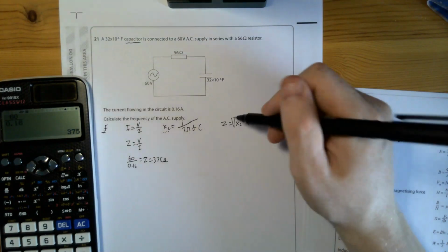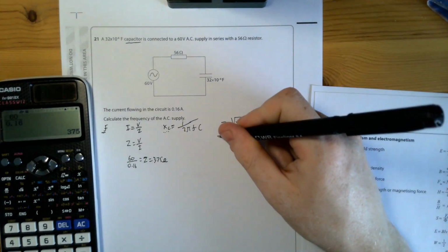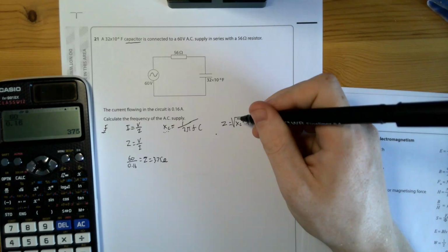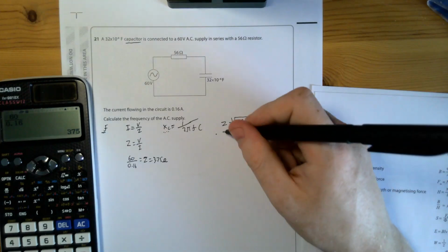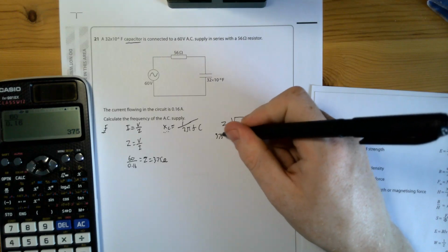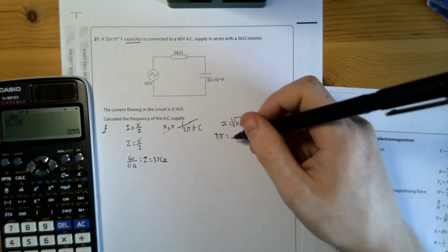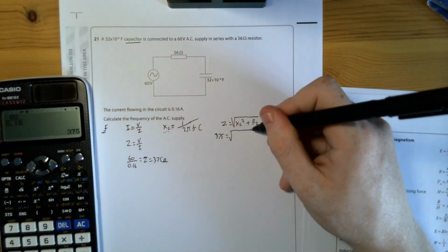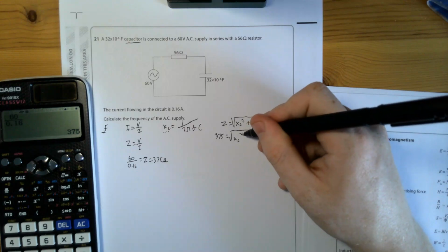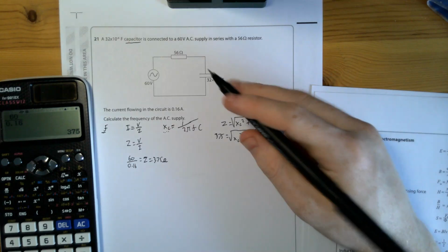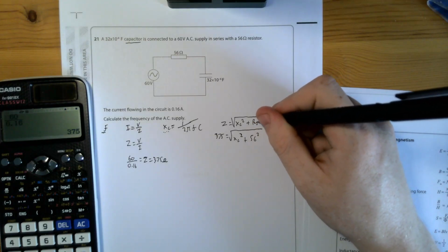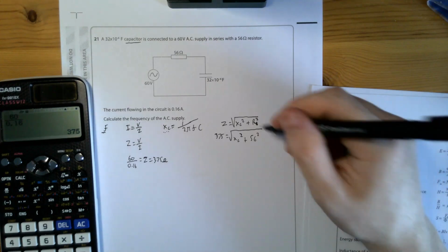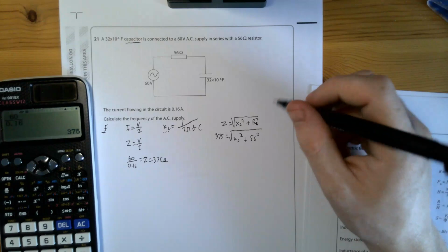Let's now go over to this formula over here. What I'm going to do is substitute my values in this time, then I'm going to rearrange after. Okay. 375 is equal to the square root of XC squared plus the resistance, which is going to be 56 squared. Sorry, I didn't mean to write the 2 there, I meant to write the 2 up there, but not subscript, I wrote superscript because that was the value that's going to be squared.